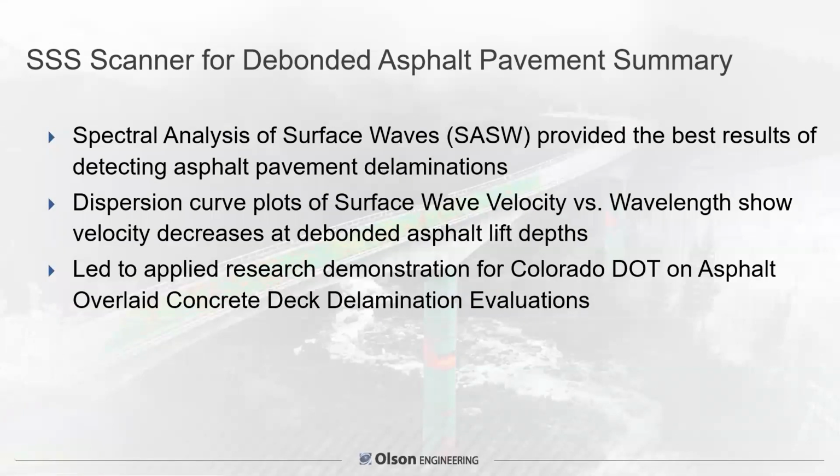So from this, we were able to map out very well debonding of new asphalts when the tack coat doesn't take between lifts of an asphalt pavement. That led us to demonstrate the technology for the Colorado DOT on an asphalt overlaid concrete deck.